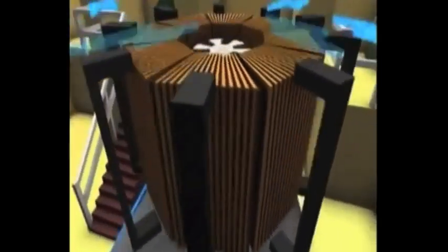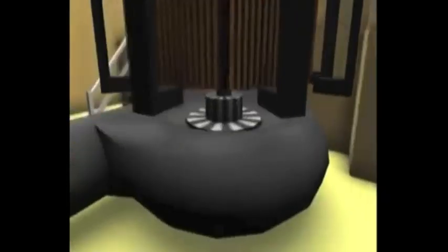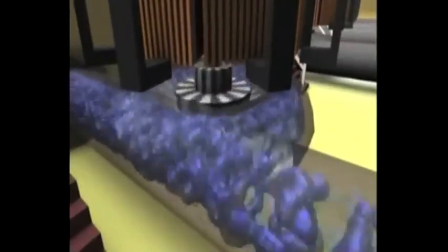Electricity is produced when the reservoir water flows into the intake towers. Here the water falls through a tunnel or penstock inside the dam. At the end of the penstock, the water hits and turns a turbine propeller which drives the generator. This spins a series of magnets inside coils of copper wire, producing electricity. Power lines then carry the electricity from the generator to a substation. Meanwhile, the water continues past the turbine propeller and empties into the river downstream.